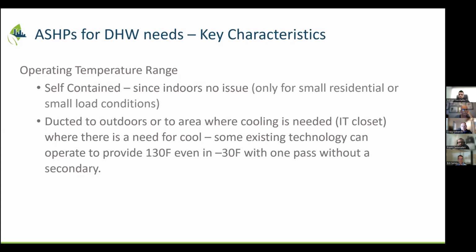Don't have much of a concern, but for the majority of ones in larger buildings, it's typically ducted to the outdoors or to areas where cooling is needed. We know that Craig has good examples where he's actually been trying to duct it to an area where there's an IT closet nearby where there's a requirement for cooling. So it's great taking advantage of the cooling that comes as a byproduct of this and using it somewhere useful